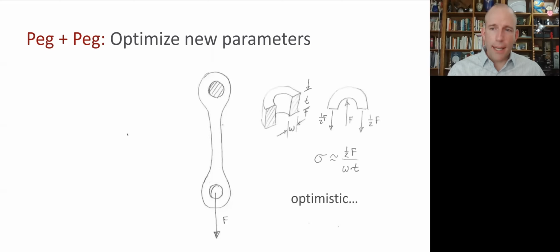And a simple way to try to capture it is to say, oh, we've got this arc over the top of the peg that has uniform width and thickness. And then we could say, well, a really simple free body diagram that could be used to get a stress answer would be to say all the forces centered in the middle, and then there's 1/2 of the force downwards evenly distributed on both sides. And that would give us a stress of F over A, where F is 1/2 of that applied force divided by the width times the thickness.